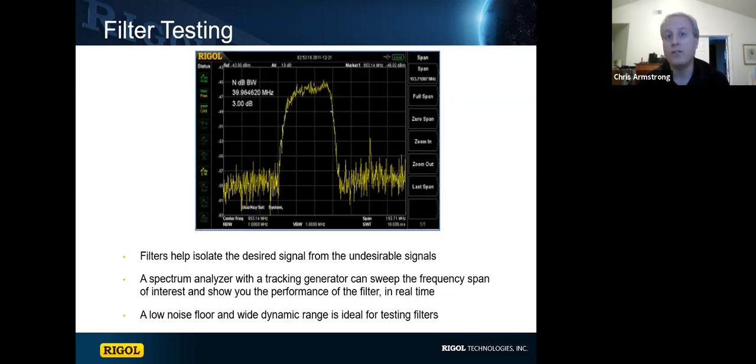If you haven't used one like this before, the tracking generator is in the scanning mode. The tracking generator is always synchronized with the analyzer, so it works across the span, putting out and reading back the power at each frequency. So you get a nice response curve across frequency.